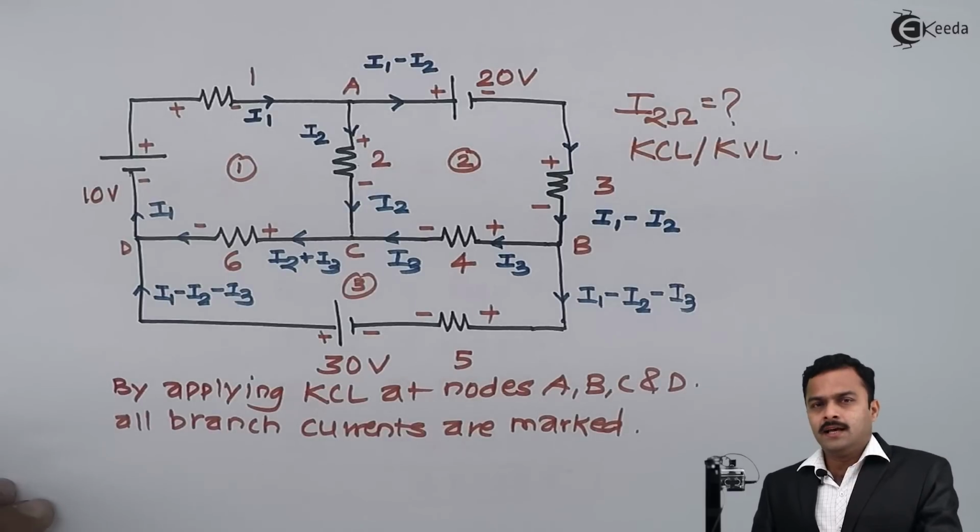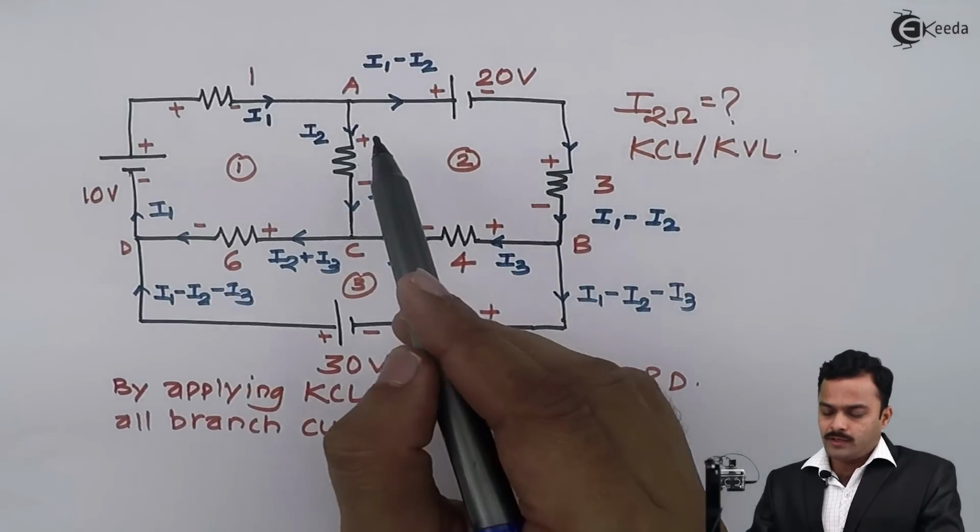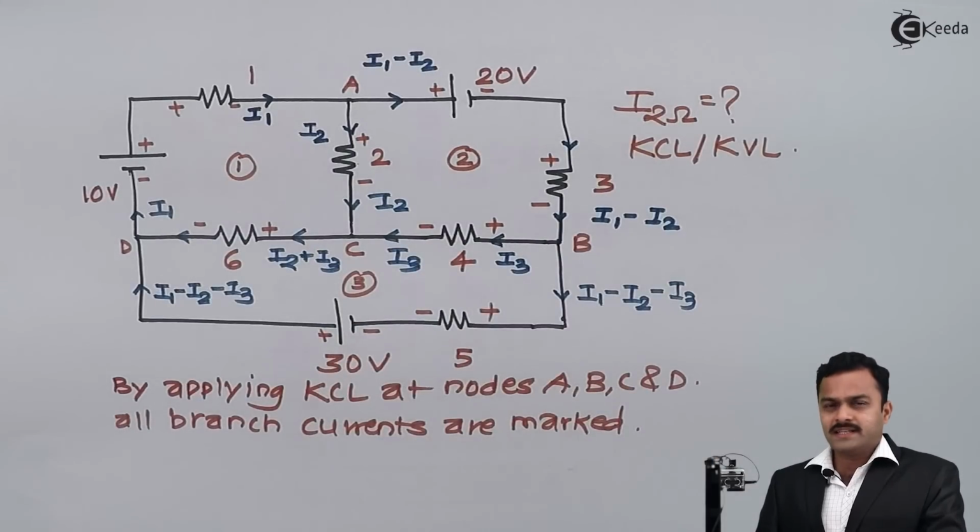So similarly we can have current flowing through all the branches. So this way KVL and KCL together can be applied to a problem to get a current flowing through any of the branches given. We will see more numericals based on this KVL and KCL. It's a modification, we call that as a nodal and mesh in subsequent videos. Thank you.